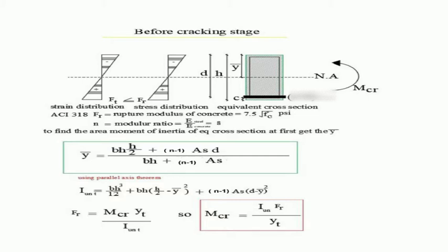It's almost equal to 8. So what is specifically the modular ratio? According to Hooke's law, the plane section before deflection remains plane after deflection. So we are still in the linear elastic region in this strain distribution. Also the steel and the concrete are bonded together strongly, so the steel and the concrete will be strained by the same amount. Hence epsilon s equals epsilon c.